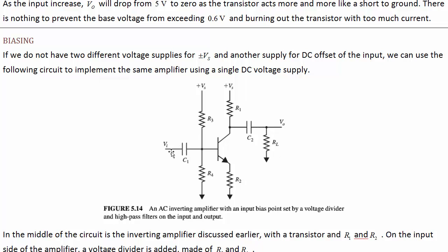So for the input RC filter, we still want to stop frequencies that are, say, below 100,000 from going into the circuit. But what's the resistance that we use? Well, from thinking about Thevenin equivalent type things, we've got a resistance in AC here of this resistor to ground. The fact that this is a DC voltage in AC, that still looks kind of like a zero.